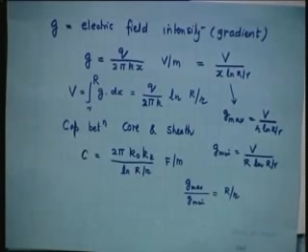Now, as I said, G was defined as the electric field intensity gradient, and you know the equation G is equal to Q upon 2 pi k x, where x is the radial distance to a point from the center of the conductor, Q is the charge we have just now defined, K also I have told you, and gradient is always given by voltage per meter.